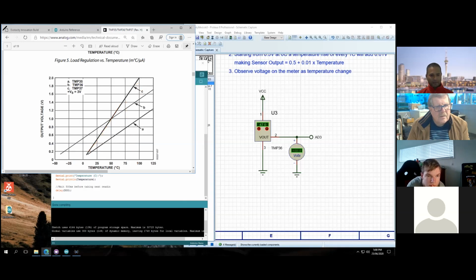It's a question of how accurate we need to be, isn't it? If you're off by a couple of degrees, we're not too worried, because we would set the alarm for the battery at a conservative number. So you're not too fussed about whether you're reading 50 degrees or 48 degrees or 52 degrees, as long as you're conservative with your alarm trigger.